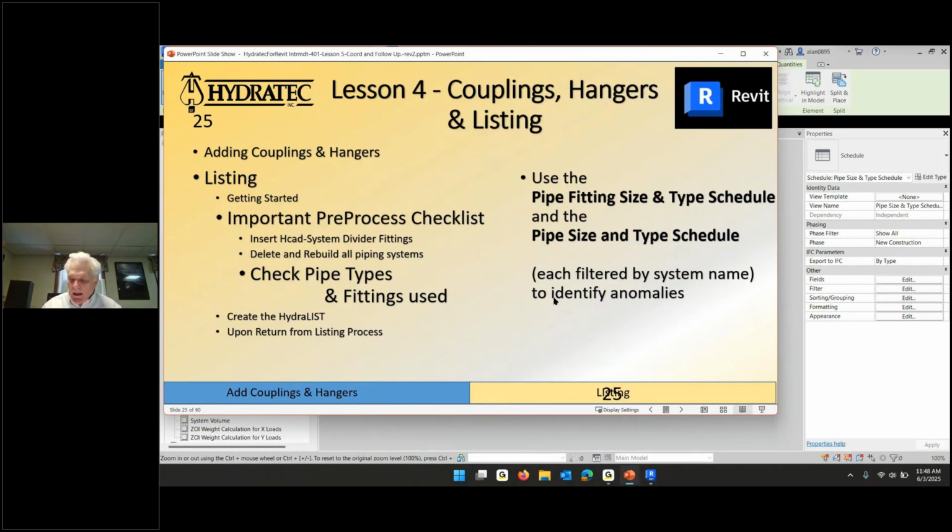The third way that you can use delete pipe is have nothing selected, and when you pick delete pipe, don't pick a pipe, pick a fitting, and then pick another fitting. The pipe between them will go away. The first fitting picked will stay put, and the other fitting will move to match it. Okay, thanks.